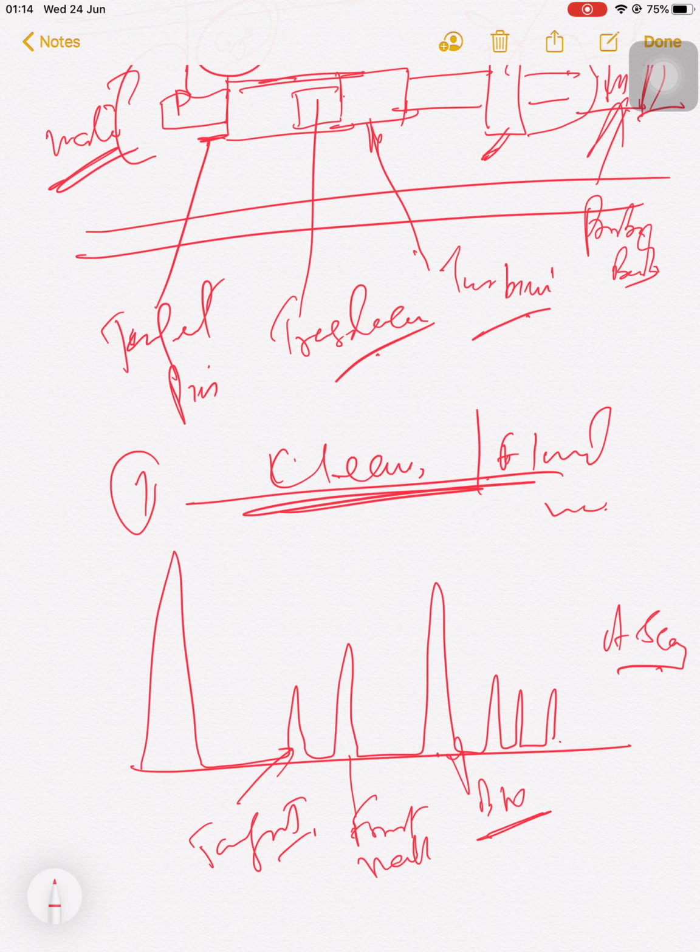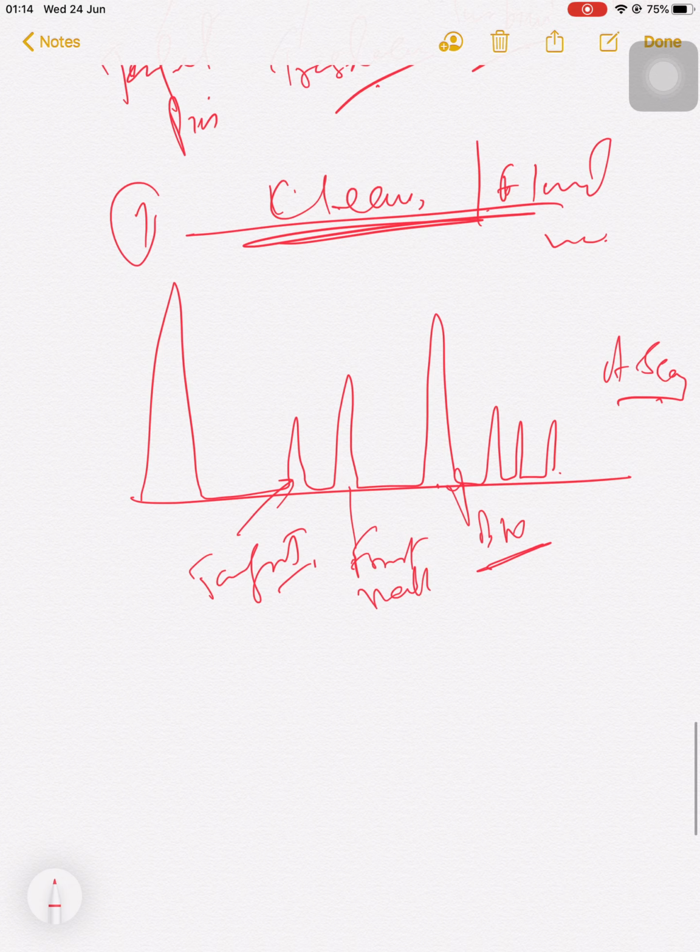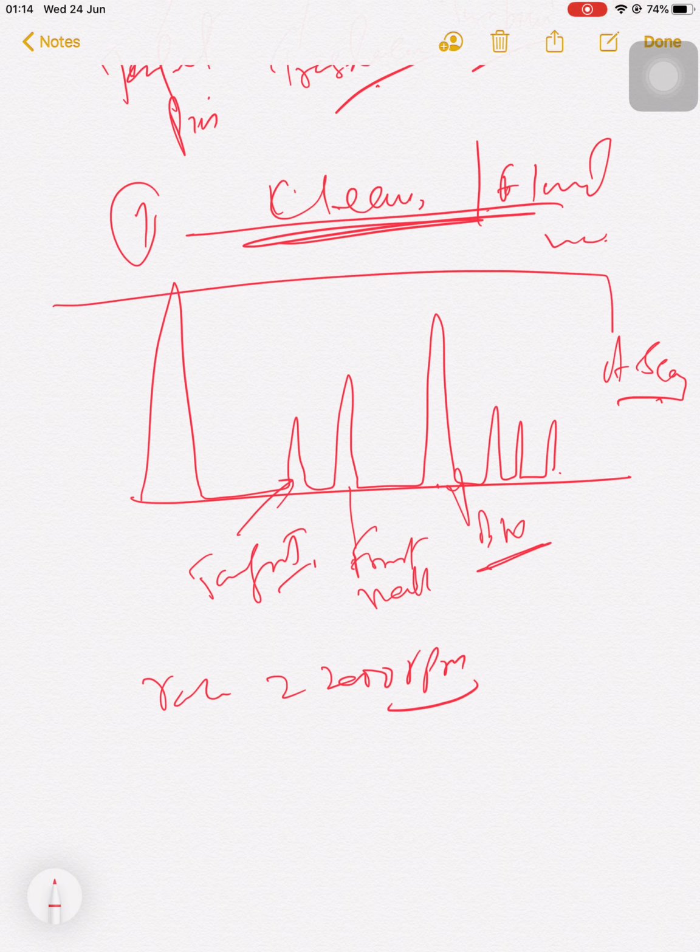As the mirror is mounted on the turbine, it rotates at 2000 rpm, and the probe is pulled through the tube slowly. The whole tube surface is tested. For better understanding of this we can analyze.